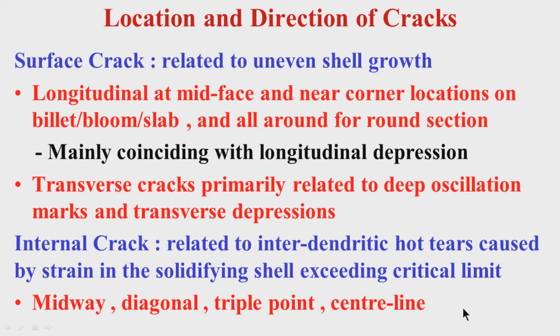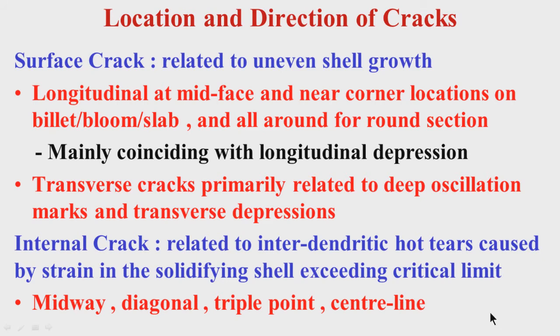I have mentioned how center line defects, segregation, cracks, shrinkage cracks, or too much porosity can be controlled to some extent by using mechanical soft reduction. I had also mentioned it has to be of certain intensity, and the location where you put the reduction is very important. It cannot be just anywhere, it has to be near the end of the solidification zone, where final solidification is taking place. In that area you put pressure, some reduction in thickness, not suddenly but slowly in steps. There is a gradient of pressure development at the final solidification front. In that process you can reduce the intensity of defects at the center line, whether cracks or pronounced segregation.